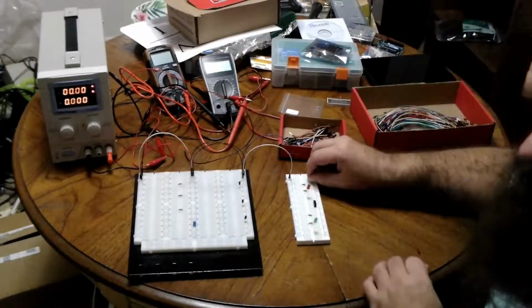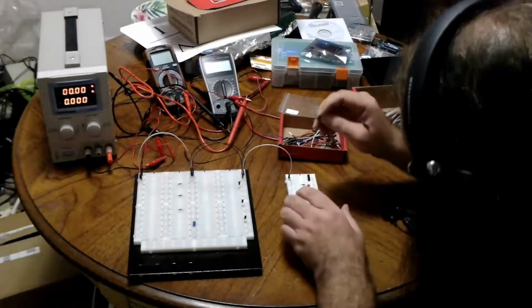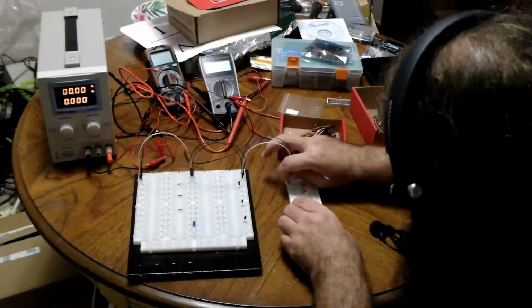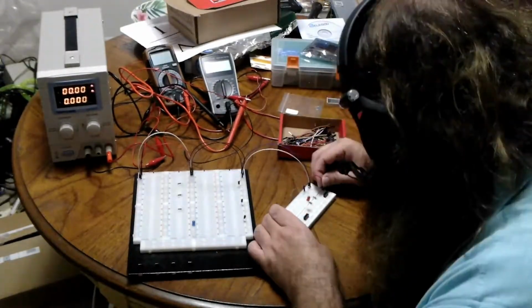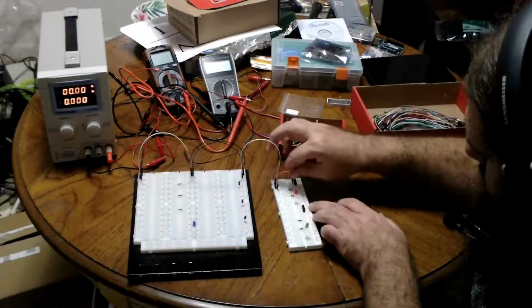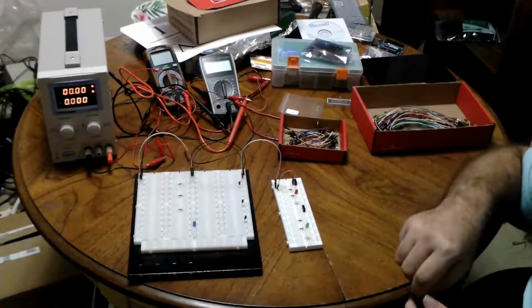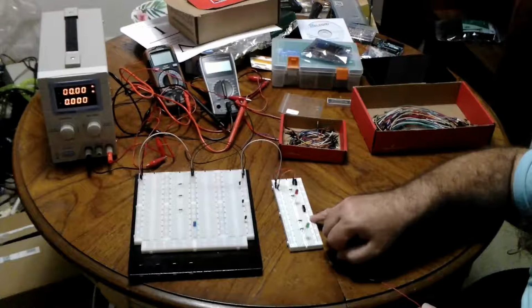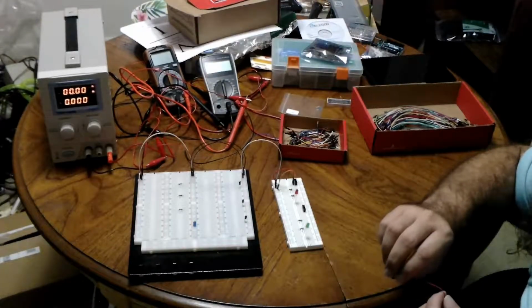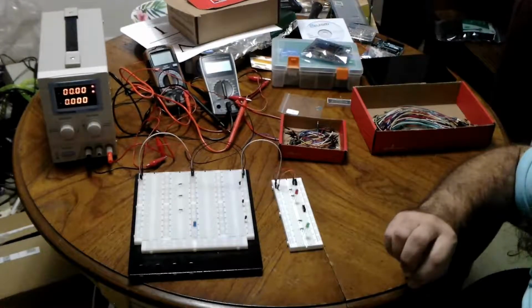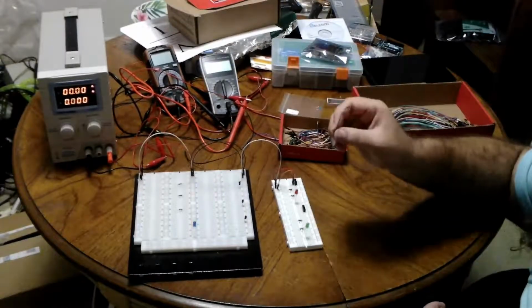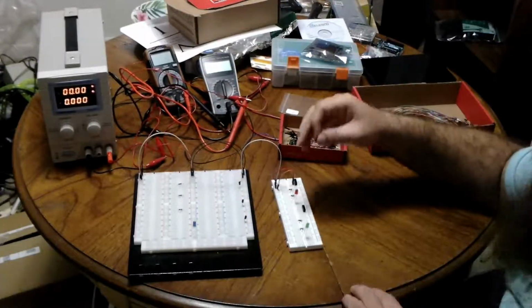So the switches will connect either positive or negative to their middle pole. So we'll go positive to one side of the switch, negative to the other. And when you're working with this many wires, remember, if you have a failure in your final circuit, start using your multimeter and measure voltages because you're likely to have bad wires. I have had that fail many times, or sometimes they're just loose.